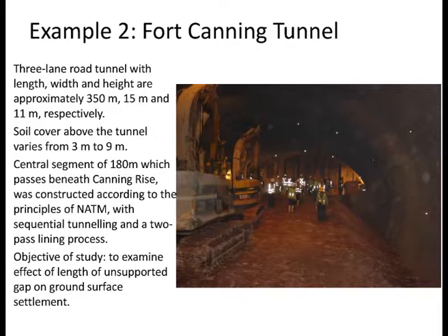So this Fort Canning Tunnel is very special. It's only 180 meters, I think. It passed through a hill, the Fort Canning Rise hill, very close to the center of town. And the tunnel is not very deep. The deepest portion was 9 meters below the road. The shallowest portion was only 3 meters below the road. The tunnel is typically about 15 meters wide and 11 meters high. It's kind of a dome shape, and it passes beneath the Fort Canning Rise.